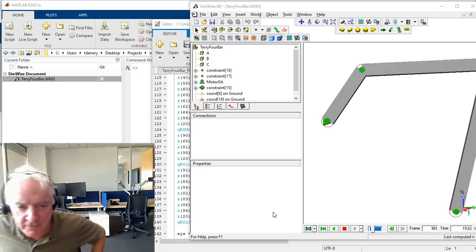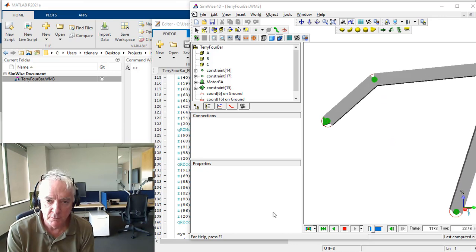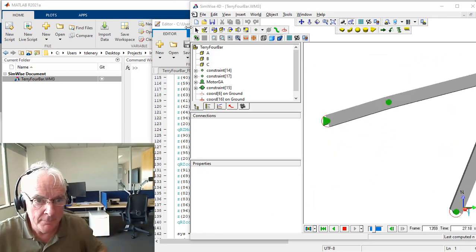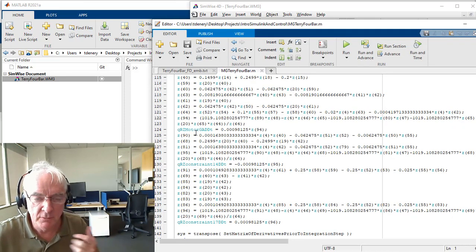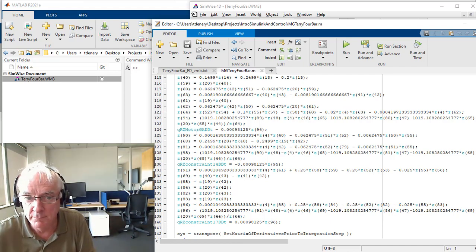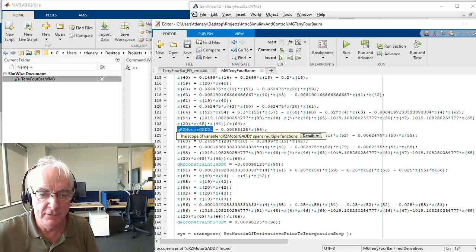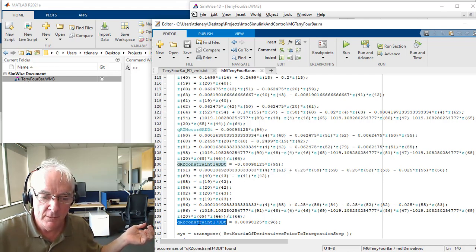In this video, called Reduce the Mechanical Model and Make It Run Really Fast, we build on the previous video, where we had a really good out of the box experience. We got essentially the differential equations and a program solution in .m MATLAB form. It solved the second order differential equation for each of our revolute joints, and there are three of them. We'll talk a little bit about what the fourth one is in a moment.